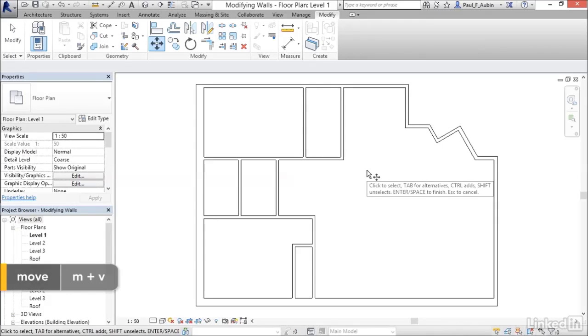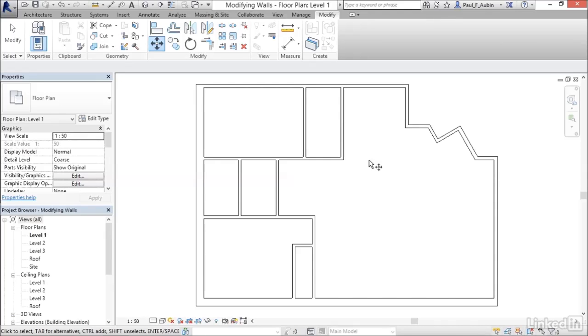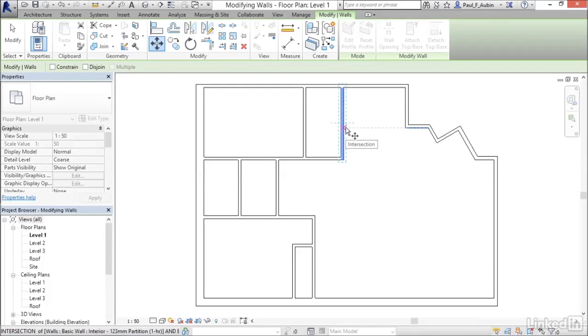And if you click the command first, what'll happen is Revit will then prompt you for a selection because I don't have anything selected. So I would have to select some object, and then in order to complete selection, I have to indicate that to Revit either by right-clicking or pressing Enter. So now I'll press Enter. The next step is to decide what point you want to start the move at and then where you want it to end up. So you're basically picking the object up, you're going to walk with it, and you're going to put it down.